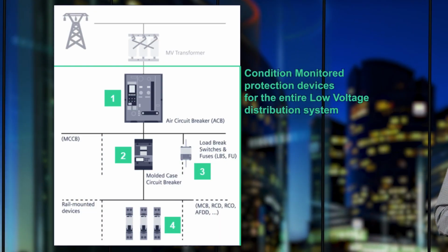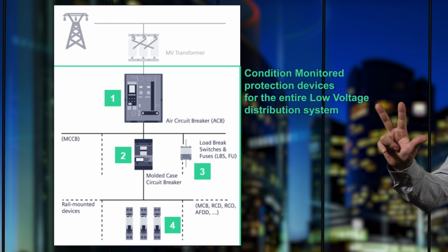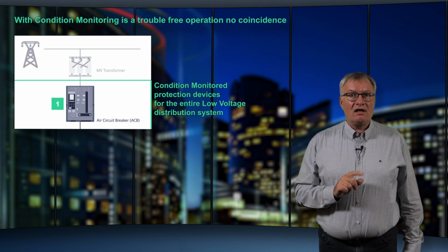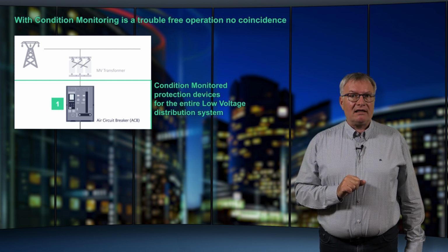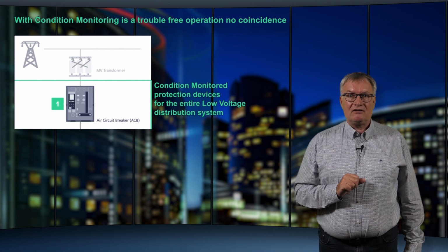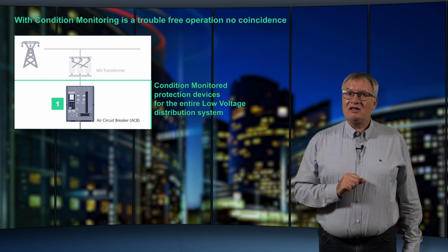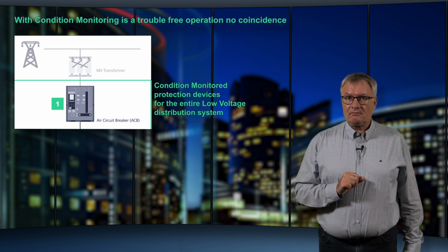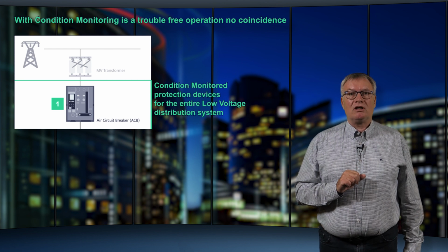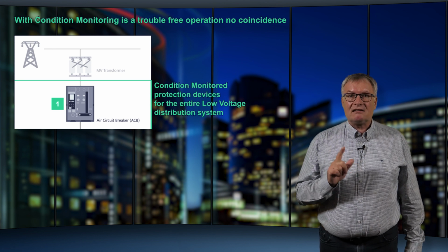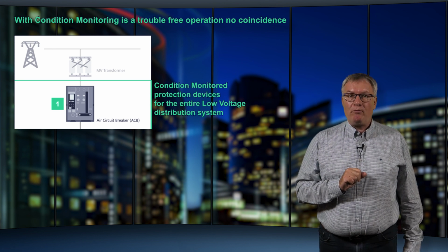This schematic graphic shows a low voltage system with 3 levels. ACBs, if operated under the specific ambient conditions, usually do not require maintenance for many years. However, they are subject to an electrical and mechanical service life with regard to the switching cycles. Both long-term and short-term events can cause a lifetime reduction. Therefore, the device temperature, the switching cycle, the number and types of protection trips, besides the condition of the main contacts, are permanently monitored.